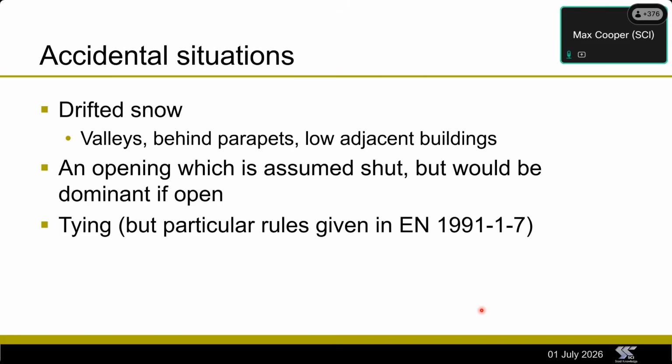The result of this is that if, let's say, you're designing a portal frame with a parapet, you probably find that the main steel members will be governed by your fundamental design combinations. That's using load factors of 1.35 and 1.5 on the variable actions.